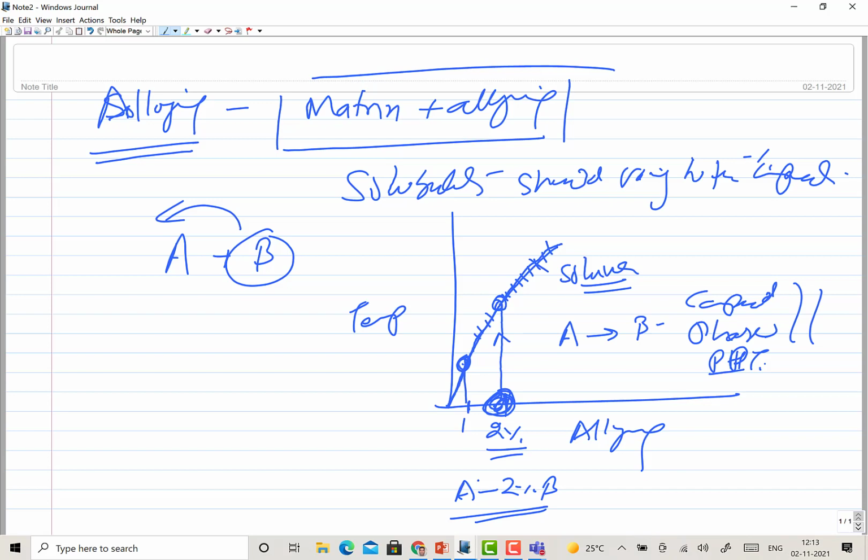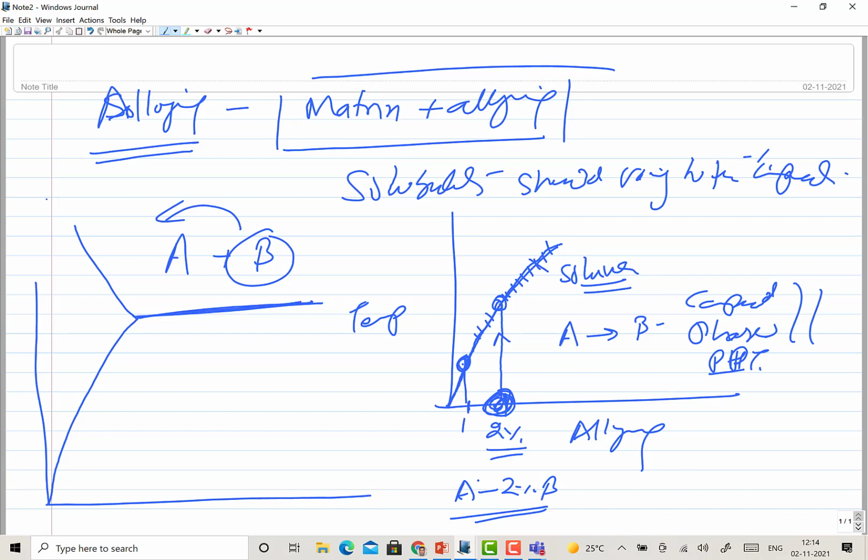Okay, so what kind of thermal cycle do we follow in precipitation hardening to form the fine precipitates? See, we go through this simple cycle. Say this is the solvus line, this is a particular phase diagram of a metal system. So the alloy composition is this, and when you heat it up to this temperature, everything gets dissolved. When the heating of an alloy is done to form the homogeneous solid solution, by heating to the high temperature, this process is known as solutionizing.